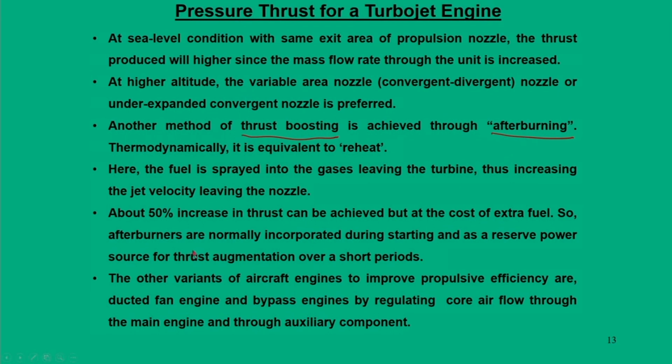So the afterburners are normally incorporated during takeoff, where we require higher initial thrust, or as a reserve power source for thrust augmentation at the time of need. In fact, whenever this afterburner is used, it is used for a very short period. We just switch it on for maybe a few minutes, and then we switch off the burner.